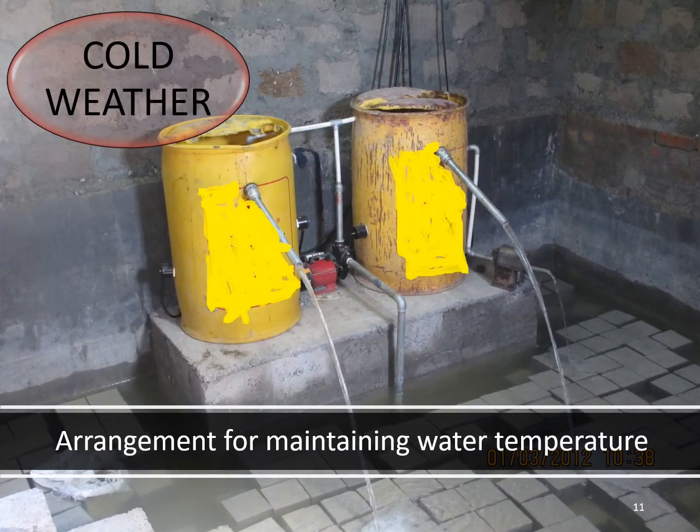But in cold weather conditions, when the ambient temperature goes below say 5 degrees or 3 degrees, then the water temperature also drops to the same ambient temperature. So especially in the cold climatic conditions, when you need to run your curing tank, especially in the laboratories where, because of the production of concrete, you are always generating the cubes, and you need to test those cubes for 7 days and 28 days. And if the curing tank water temperature is say not 27 plus minus 2, but it has dropped to 5 degrees, 3 degrees or 10 degrees, then